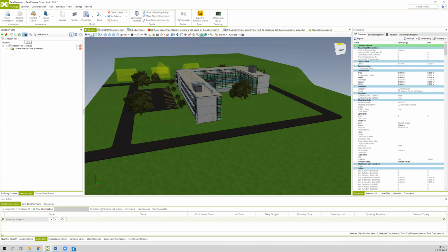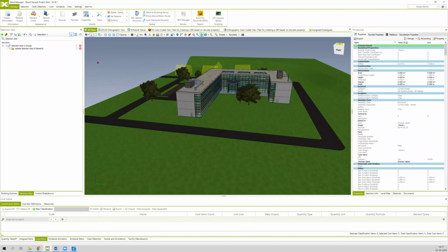And then you have also a manage selection sets command, which enables you to move selection sets, edit them, and add new folders. So in the first step, we will create 2 different folders, which will be named regular selection sets and smart selection sets. So go to the command line of the selection sets palette and click on the manage selection sets command.